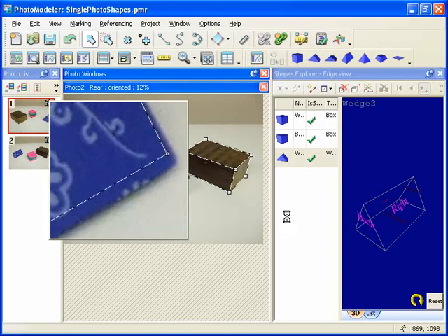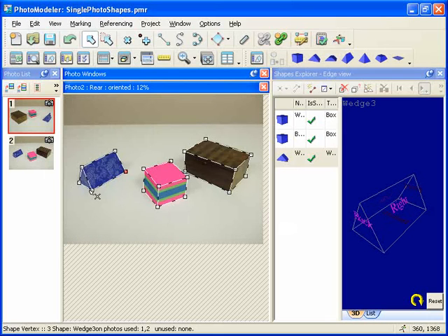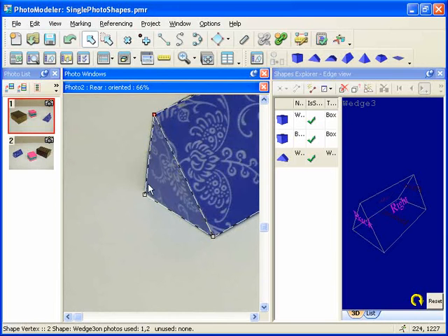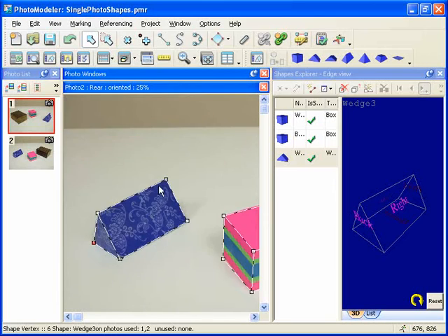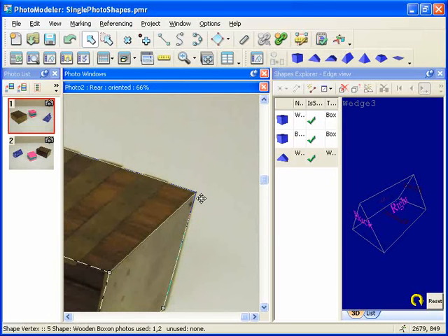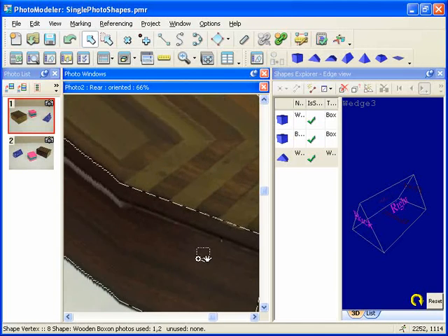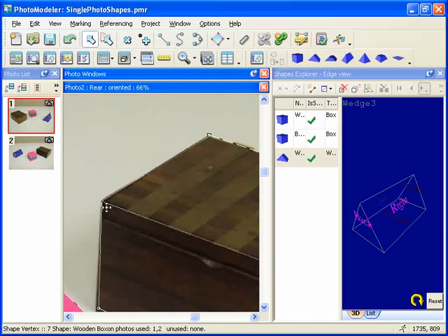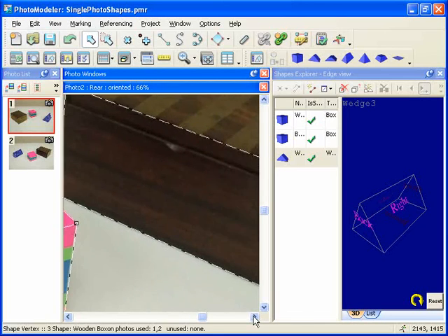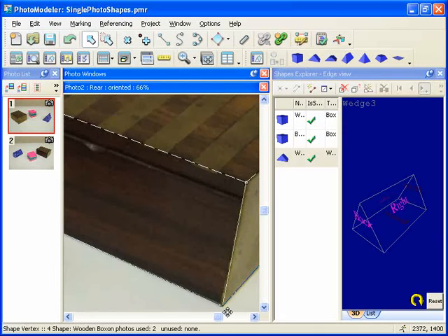We can use the Alt Zoom as we did previously. Drag the point to its correct location, or we can use one of the other zoom techniques, such as using the plus and minus keys to zoom the entire image. A similar method is using the scroll wheel on the mouse. If you hold down Control and right-click drag, you can pan the image, or we can use the scroll bars. The points in Photo 2 look good.